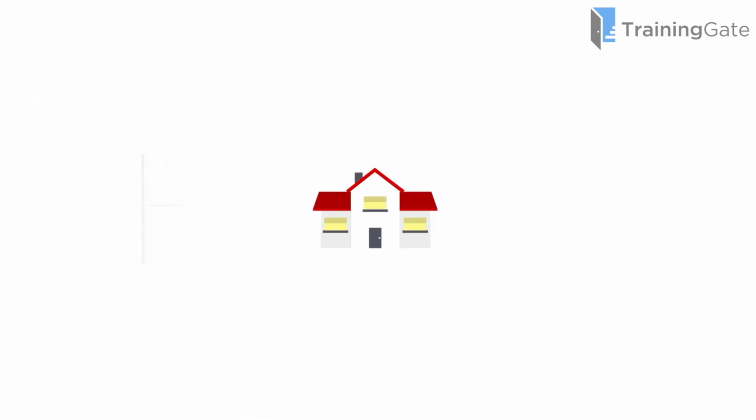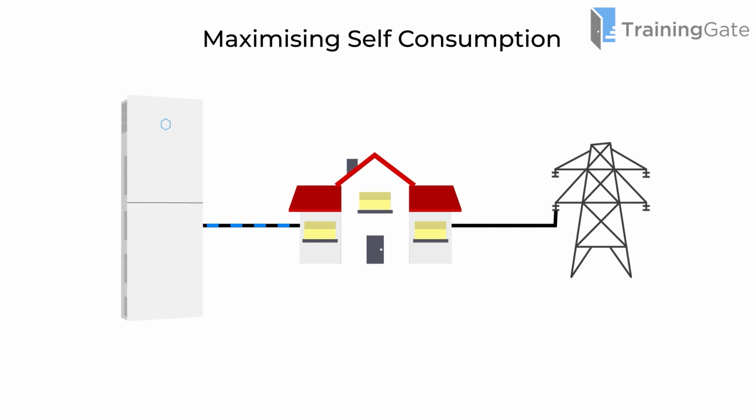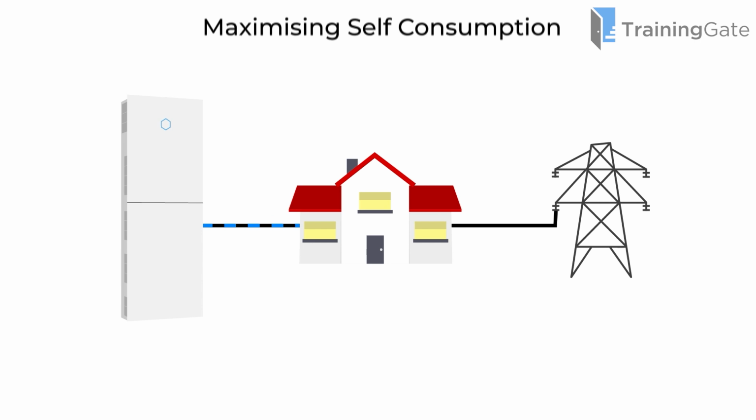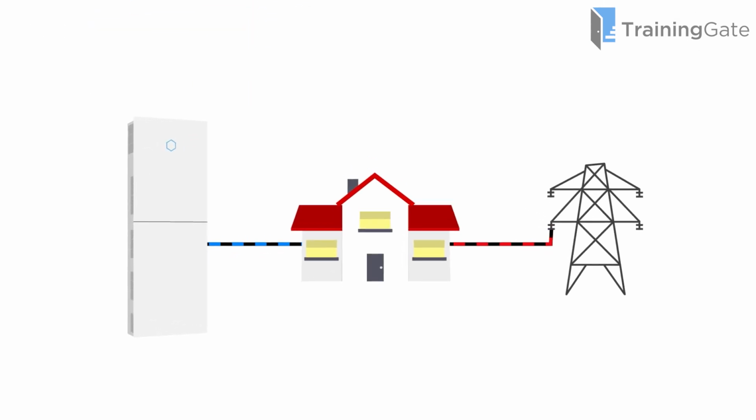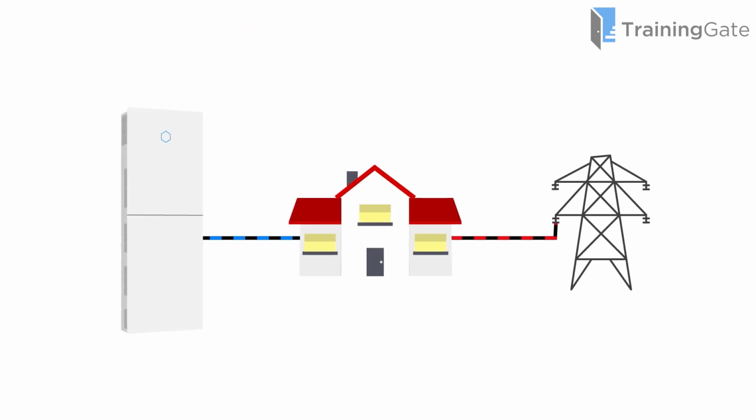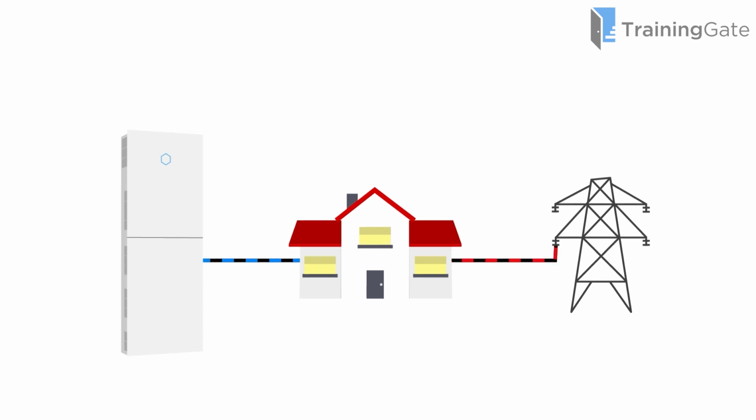For battery systems that assist in maximising the site's self-consumption with no backup requirements, the inverter should only be sized to meet the continuous supply. In these cases, there is no benefit in meeting the peak power ratings of the site, as this is supplied from the grid to reduce stress on the batteries and prolong its operating life. As a result of this, there is little need to oversize the inverter, as it operates in parallel with the grid.